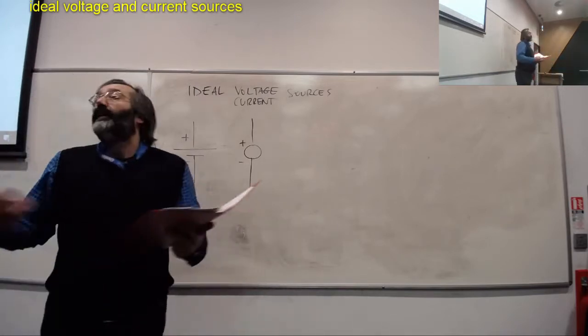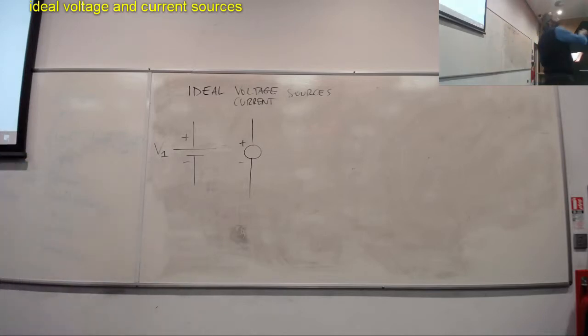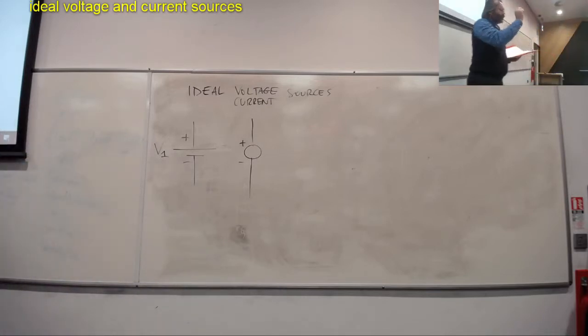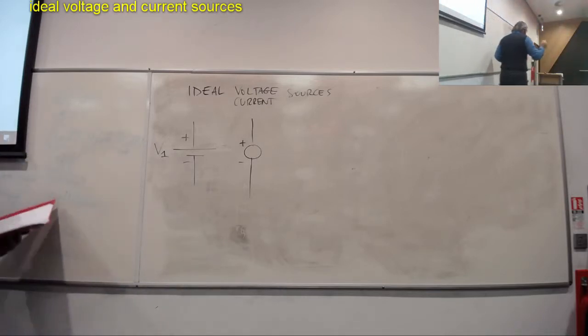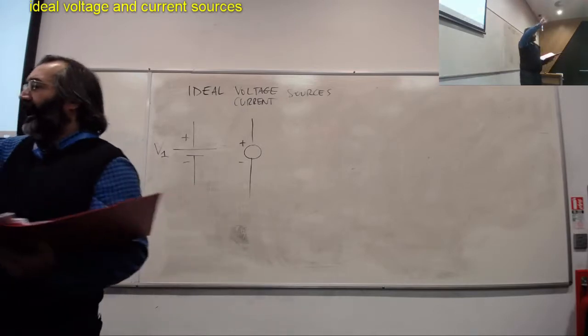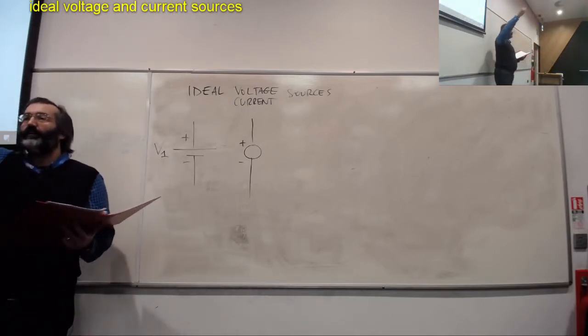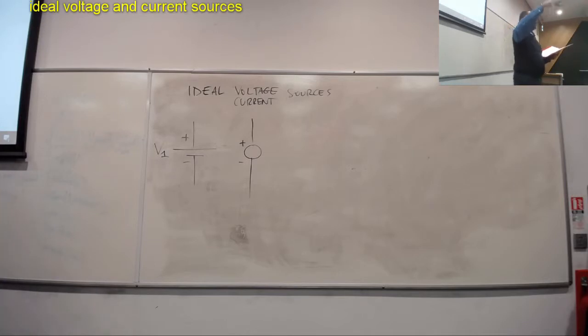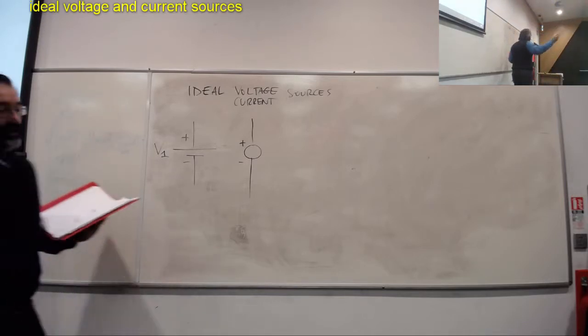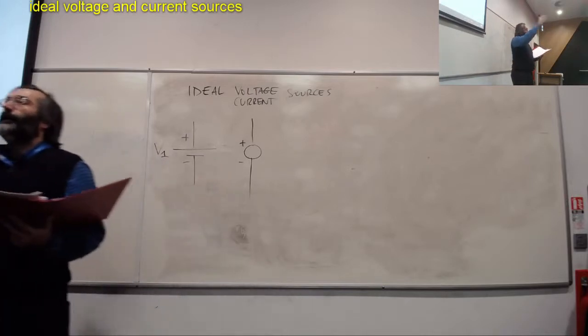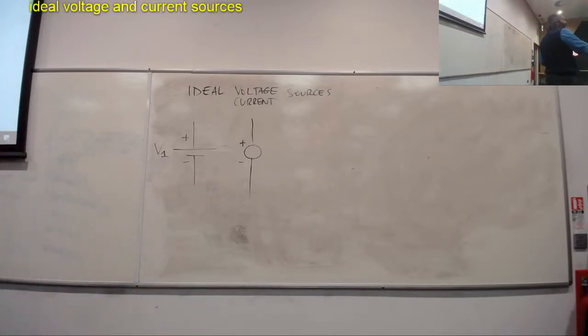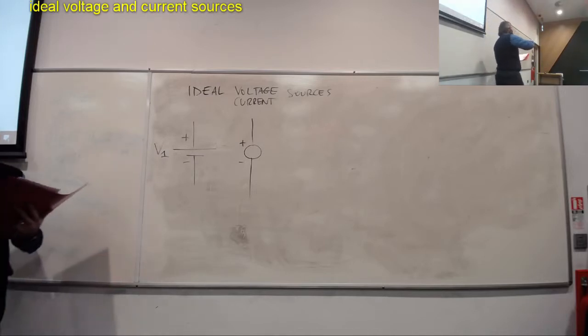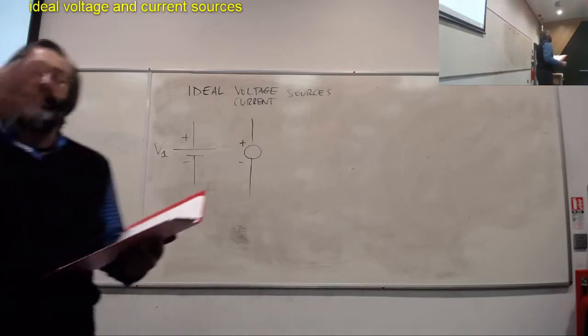And as with any electronic component, because of what we've said previously, I forgot to stress this point: under the two assumptions that dq internal over dt is 0 and the flux linkage dphi over dt is 0, we simplify things, and we don't need to use Maxwell's equations and so on. We can end up with KCL and KVL, which we will analyze.